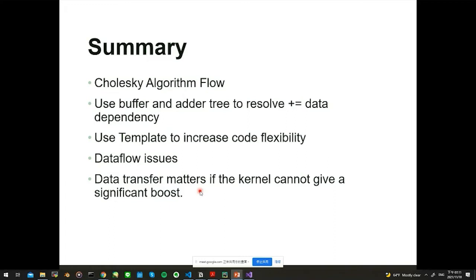So this algorithm does not really fit the parallelism. I think the parallelism is mainly from the unroll. You unroll 16 times. Since you unroll the function, it actually duplicates the function 16 times, and the hardware resource will explode.